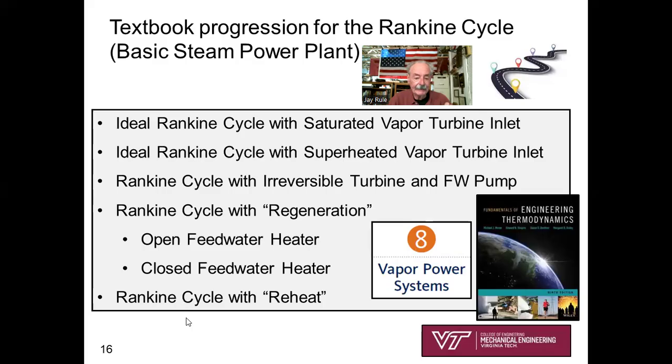And then finally, a last topic is reheating the steam. Once you go into the turbine and get some power out of the steam, you take that stream and go back to the boiler, reheat the steam, and then go back to the turbine. That can be a little complex, but you're going to have homework problems probably with all of these examples of regeneration and reheat.